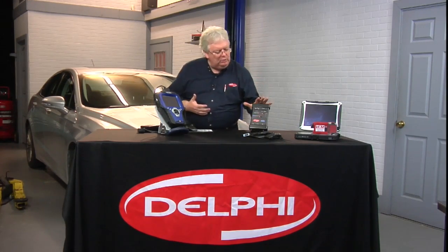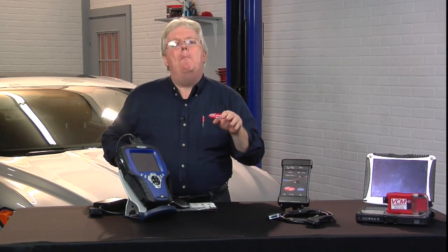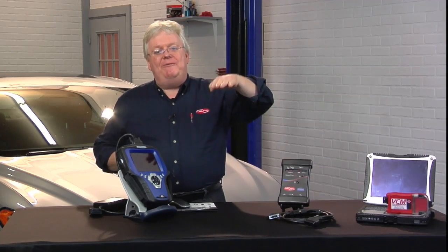I know on our tool, we have a page in one of the OBD II enhanced powertrain menus where you click on monitor requirements, and it actually gives you by monitor all the different things you've got to do. There may be some monitors that are simple, get up over this speed, over this temperature for 30 seconds, and other monitors are more like a complete drive cycle to run all the monitors where you're doing different speeds, different temperatures over the course of, let's say, a couple of different occurrences. So that's going to vary very much. It's really a difficult question to answer simply.